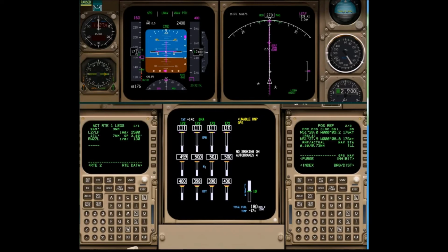If this message comes up on an RNAV, you have to discontinue the RNAV, either change it for another type of approach which might be compatible, or carry out a go-around. If you decide to continue with the approach for any reason, or you miss the message, once you get on the final approach segment, this message will turn into a caution with a beeper, so you can't miss it.